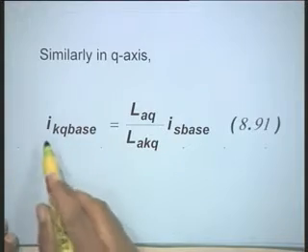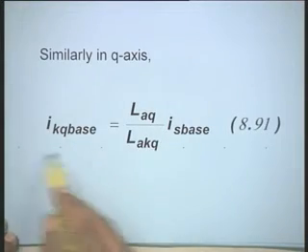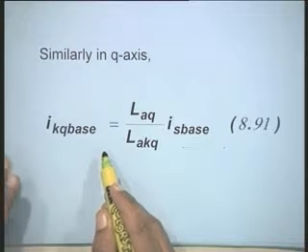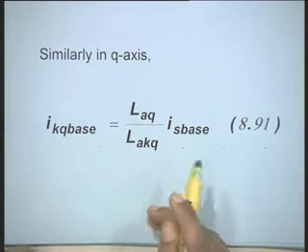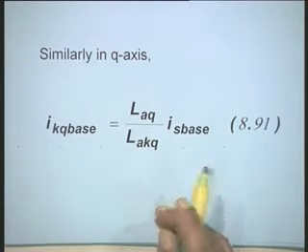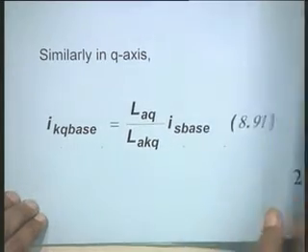And therefore, when I talk about the VA, that is the field voltage base into the field current base. Okay. Now, this product is equal to the 3-phase VA of the stator, right? But the individual currents will be defined by this expression. Now, once the current base is given for the circuits, we compute the voltage base for the rotor circuits using the previous relationship. I hope it is clear to all of you.